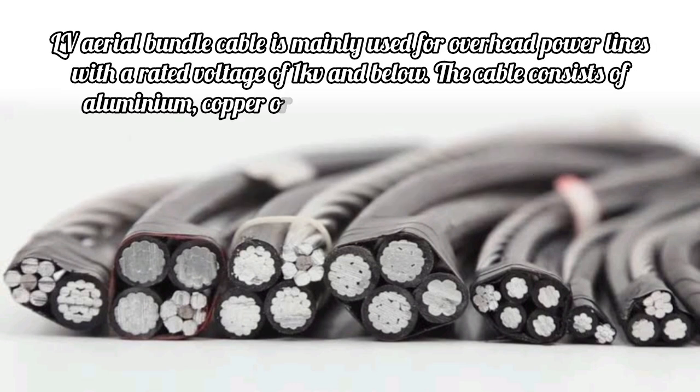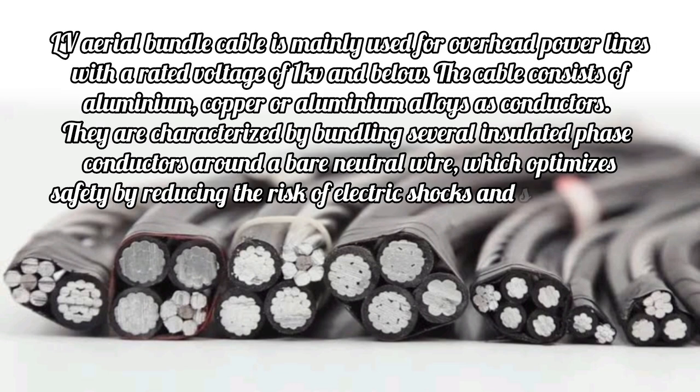LV aerial bundle cable is mainly used for overhead power lines with a rated voltage of 1 kV and below. The cable consists of aluminium, copper or aluminium alloys as conductors. They are characterized by bundling several insulated phase conductors around a bare neutral wire, which optimizes safety by reducing the risk of electric shocks and short circuits.